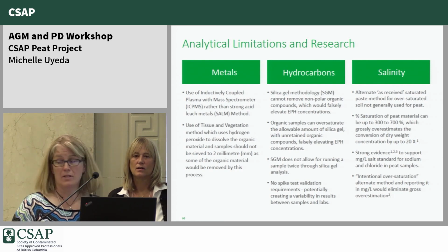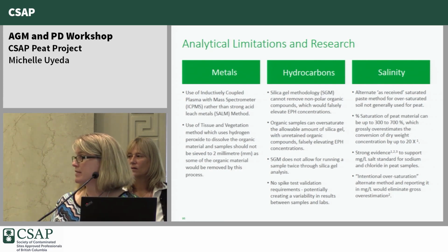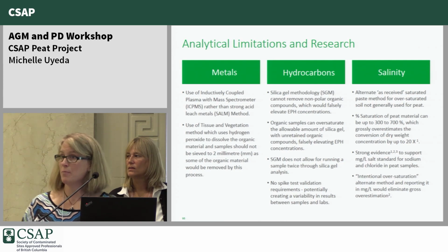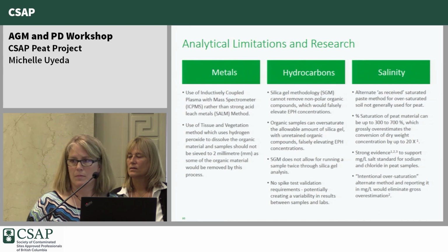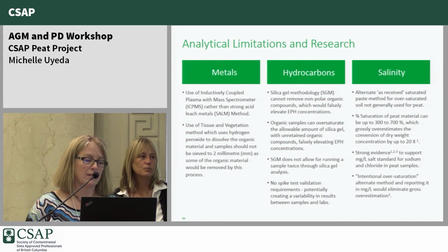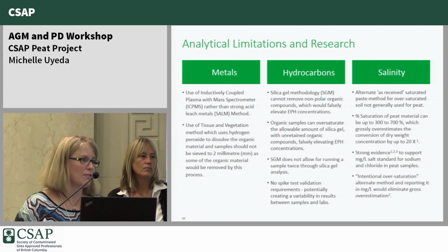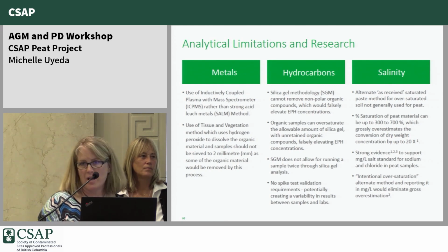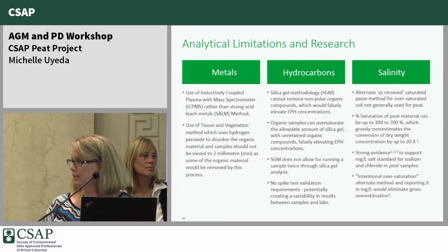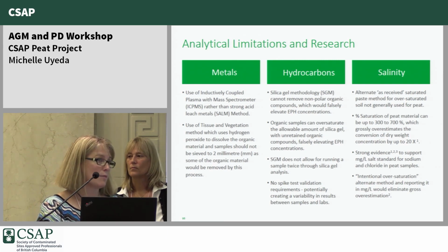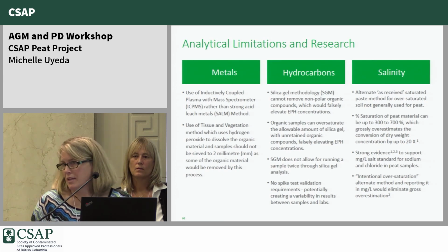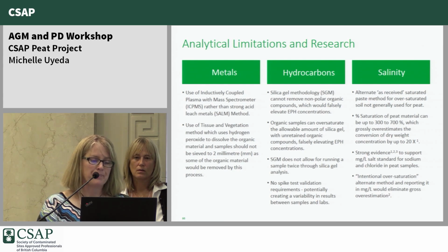With respect to hydrocarbons, we know that here in BC we have the EPH silica gel cleanup, which helps to remove some of the organics and to reduce the falsely elevated EPH concentrations. However, what we've surmised by asking practitioners and the labs is that there are also some limitations with the silica gel method, and it probably could use some review and updating.